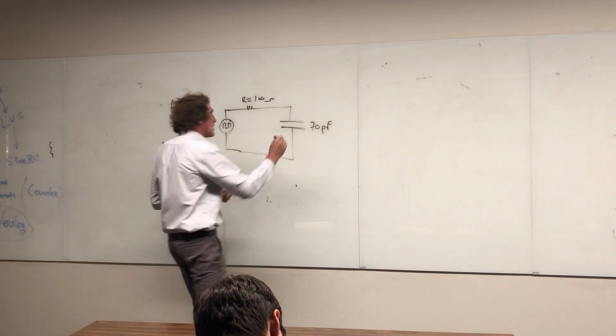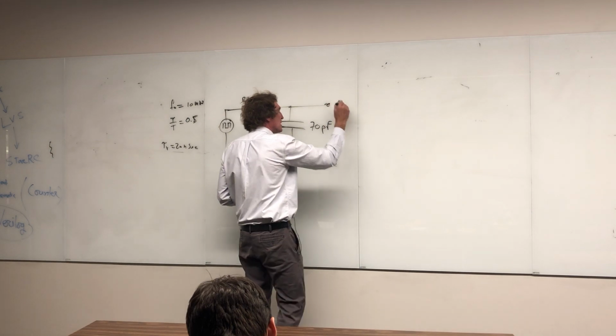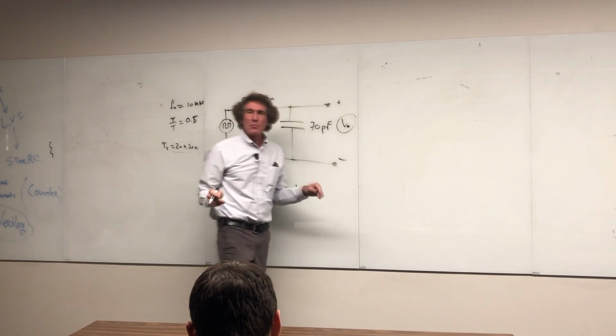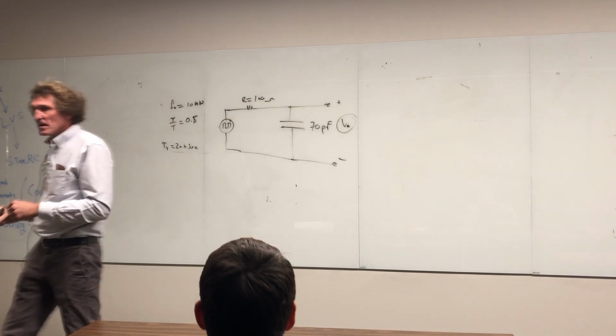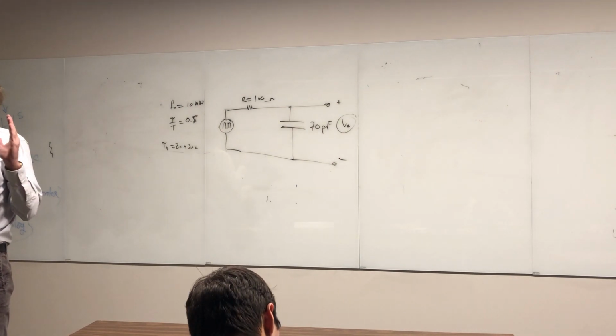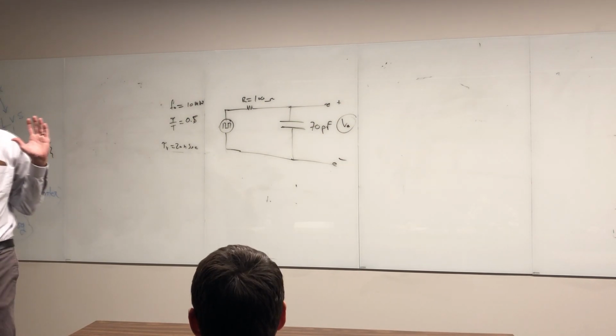Now, they want this output right here, I think, right? Is it for what harmonic? They want the 11th. All right, so they want 20 times the log of the magnitude of the output voltage at that frequency, the 11th harmonic, follow me? But it will be in dB microvolts if you look there, the answer. You all see that? This is important that you go with me on this problem completely.